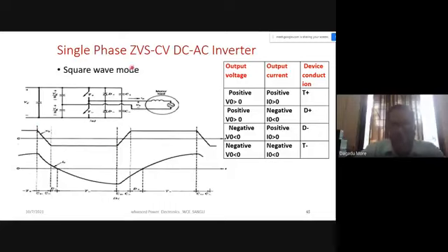Our inverter is a square wave inverter, so we are getting a single phase square wave output, and our load is an RL load, so definitely this will be our current wave shape. Current will not be sinusoidal because our input is a square waveform, and the current wave shape we have shown depends upon the inductance of the circuit and the back EMF of the motor.